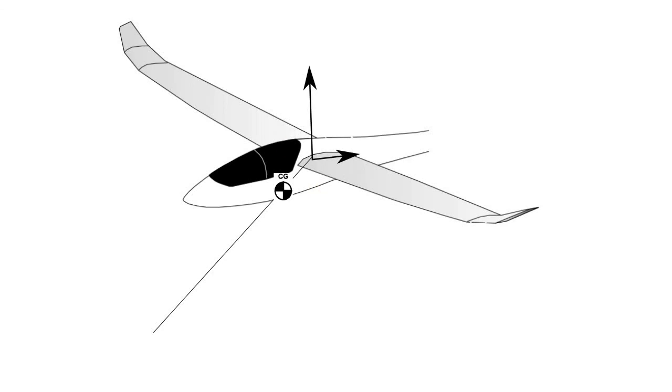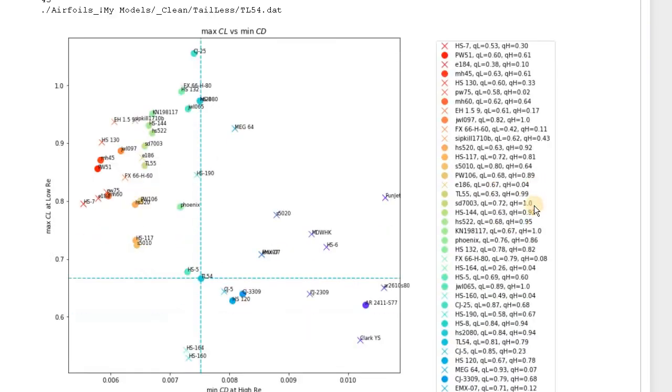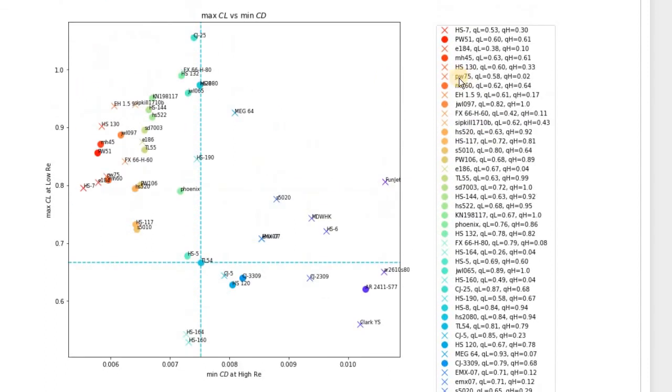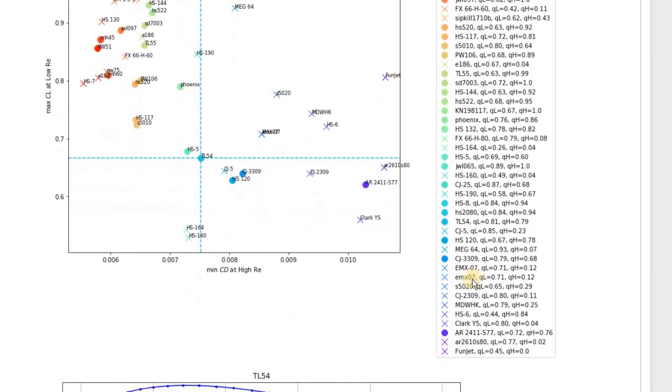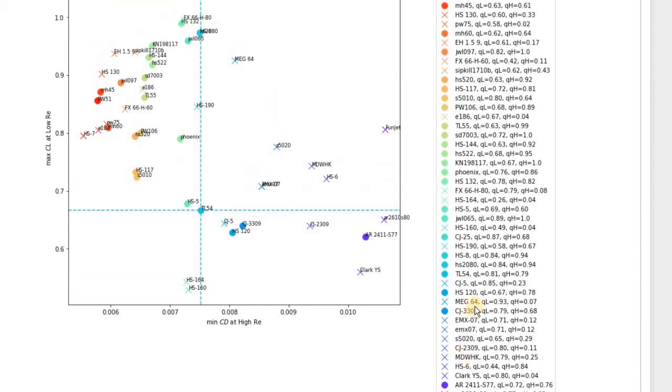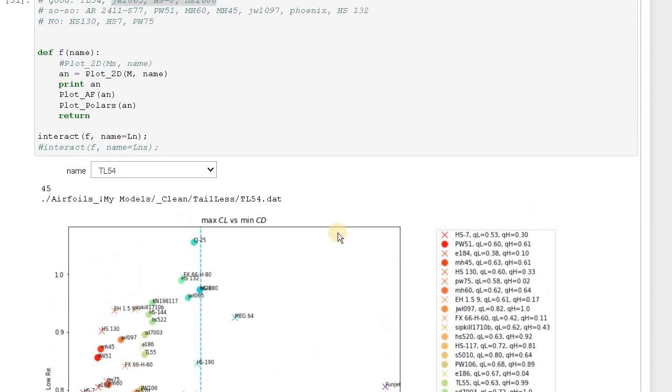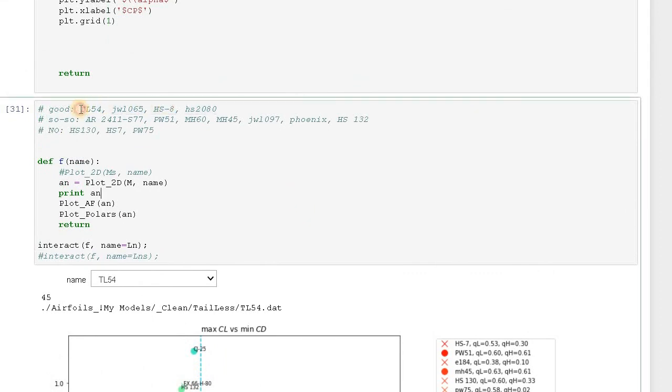And if you go to this graph, we have tested almost 40 different types of airfoils designed for tailless airplanes and flying wings, and most of them are stable, but some of them, maybe 10-20%, are unstable. So maybe using this technique we can make those airfoils stable as well. But at this moment we can say that being a simple person, we can decide to stay in 0-dimensional or maybe 1-dimensional space, and in that case we are actually bound to choose those 4 absolutely stable airfoils.